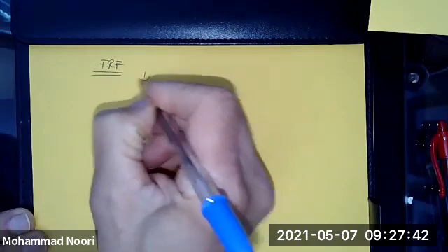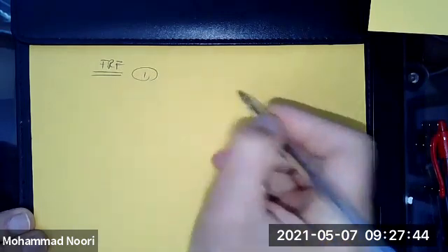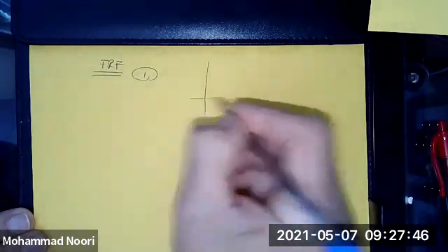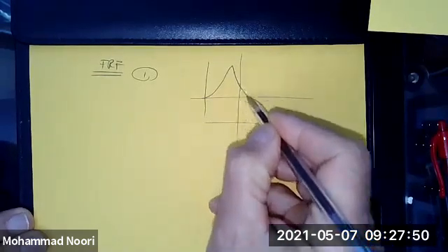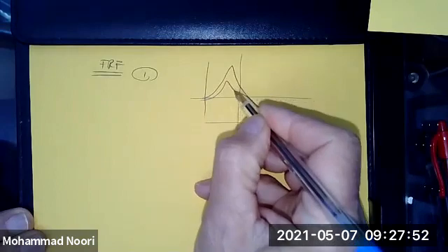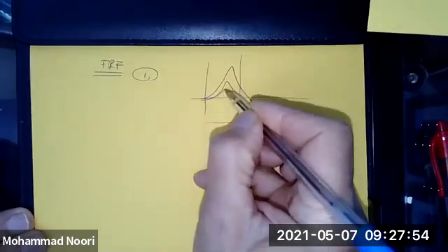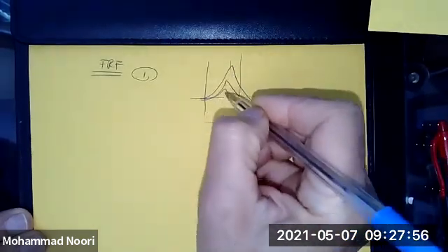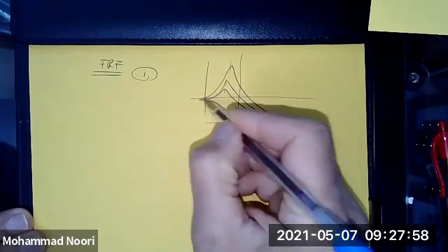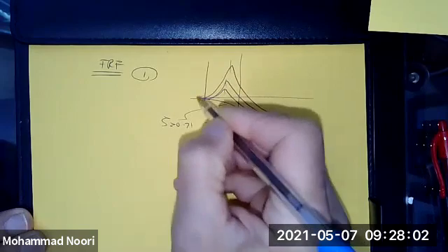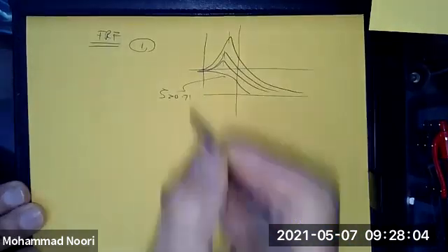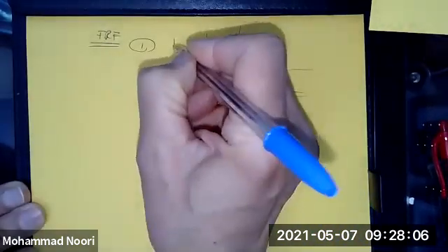For the first case, when you have a direct sinusoidal function, you have a frequency response function that looks like this. The peak value shifts to the left of r equal to 1. And if zeta is greater than 0.71, this falls below this line.